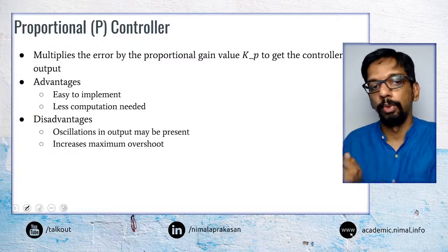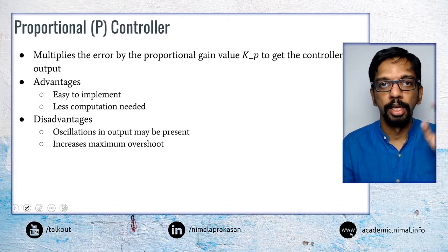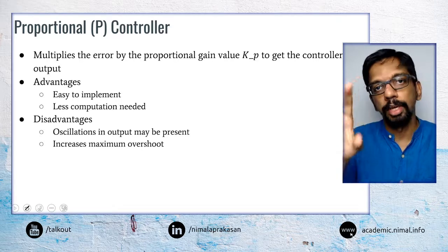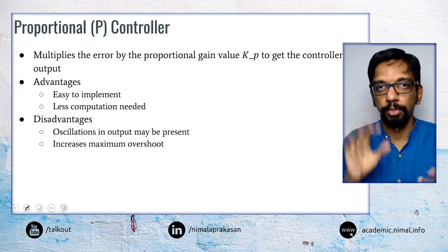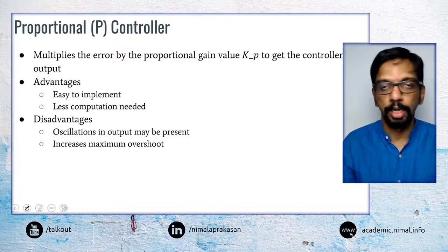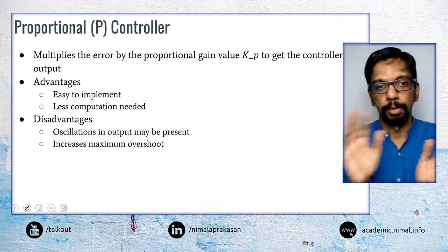That is going to be the control output, that is what we are going to apply as a brake. Say if the error is 20 kilometers, we will apply 20 times a particular variable of the brake, a particular force or whatever. If the error is lower, now the error is 10, so now the multiplication is by 10. So that is the proportional control.